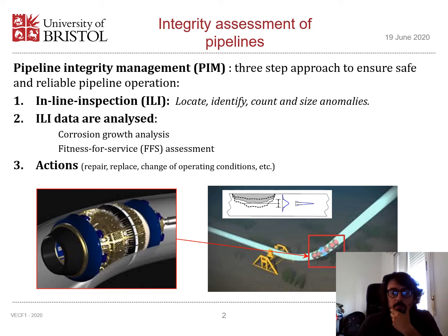That was the main project, or that's the main part of this talk. And there was a side project that was mainly targeted to try to understand how non-sharp defects can be assessed from an integrity viewpoint, so as to avoid the recharacterization of defects failing the local thinning area geometry check to be characterized as cracks.